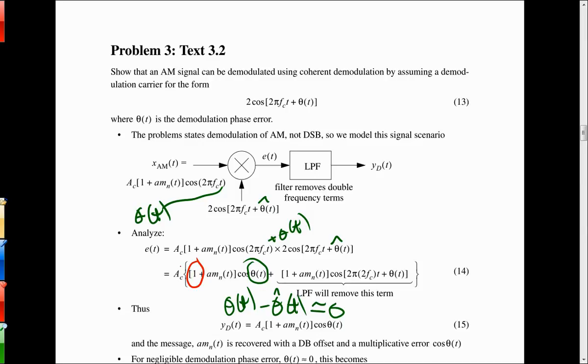A fixed phase is standing still. If perfect 0 phase is where my thumbs are overlapped, that could be bad. If it was 180 degrees, that inverts the signal, but if it's 90 degrees, then remember cosine of that would be 0. So the signals, remember from the sound demo, it nulled it out. But generally it's sliding by.